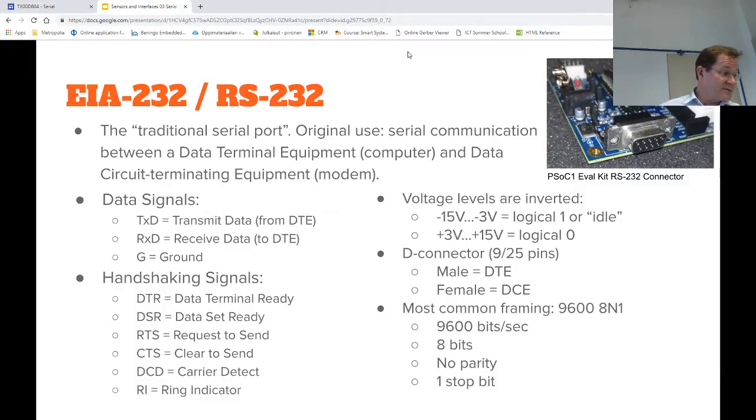And actually, the last one here tells more about the history of this RS-232: ring indicator. That is basically the standard communication channel from the era of modems. So a standard telephone line, and there you have a modem to connect the data to the line, and another modem on the other end, and one end is calling the other end, and there is a special line, ring indicator, which then basically sets the interrupt on one end, and well, magic happens.